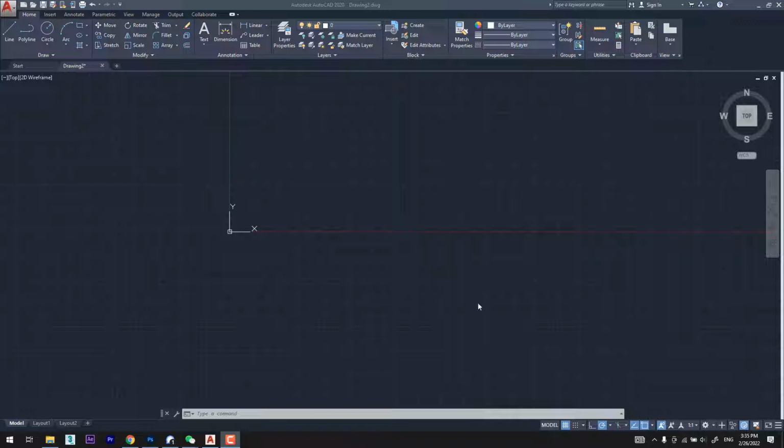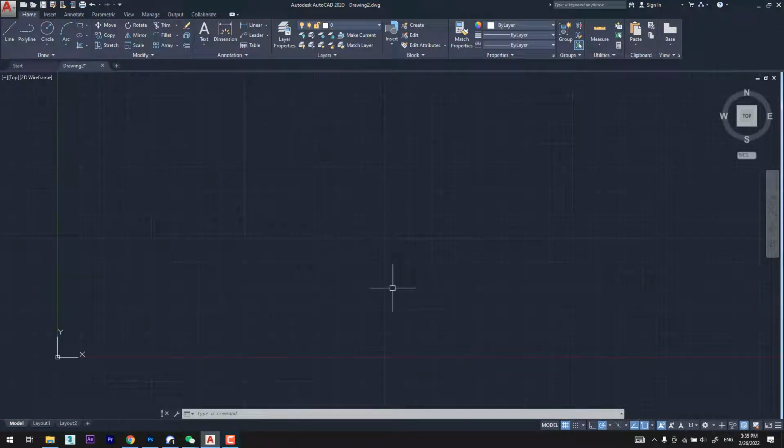All right. So this is AutoCAD when you start it. This middle mouse wheel, when you scroll up and down, it zooms in and zooms out. And when you press the middle mouse button, then it pans. This is called panning. We are doing panning, so we can adjust the line drawings, the area which we want to see on the screen. Okay.